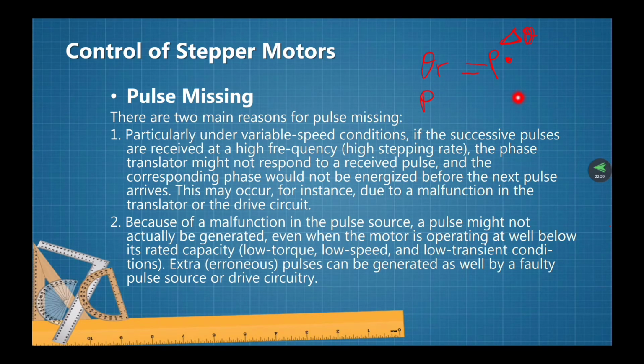In this manner, it is also possible to lose accuracy by an integer multiple of theta r because of a single missed pulse. Under adverse condition, however, pulse missing can lead to highly non-synchronous response or even complete stalling of the motor.